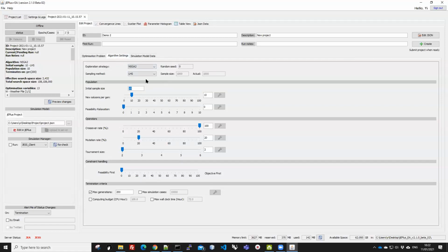Okay, now let's go to the next part, and I will only need to do some small changes in here. This is setting up the algorithm. In this tool, there's only one algorithm to choose, which is called NSGA2. Actually, in our last session, this algorithm has been mentioned. I think Yair introduced it. It's called a non-dominated sorting genetic algorithm. So this is one of the multi-objective optimization algorithms.